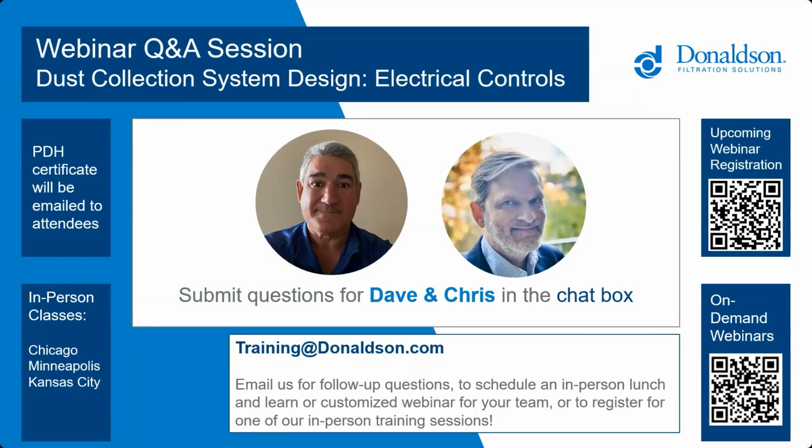So yes, blast gates are used on them. Sometimes butterfly dampers are used on them. I know that a lot of times NFPA has issues with blast gates because dust can fall on the back side of them, but if they're properly installed in the vertical orientation, that shouldn't happen. So yeah, blast gates are typically the way we do it, or making the diameter of the duct bigger or smaller to create the same amount of resistance on a drop that is consistent with it.